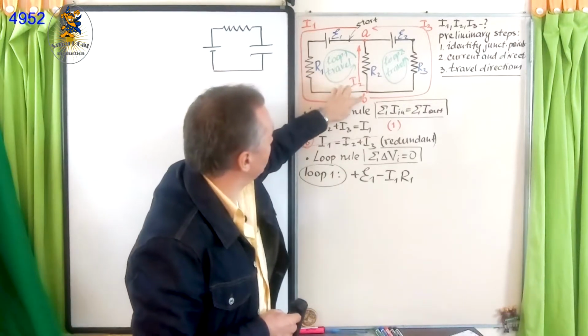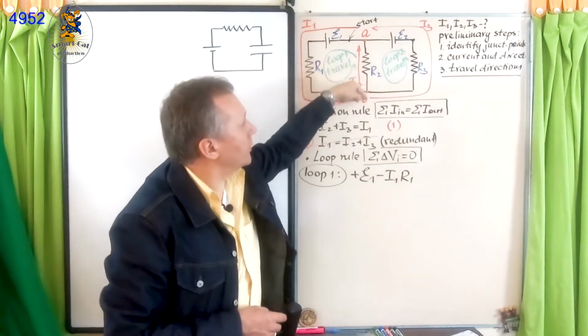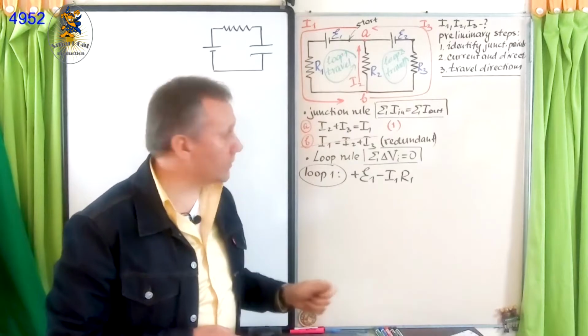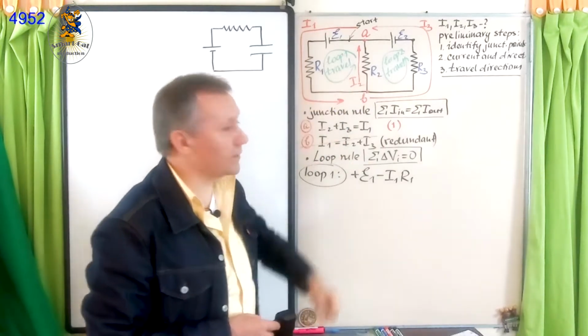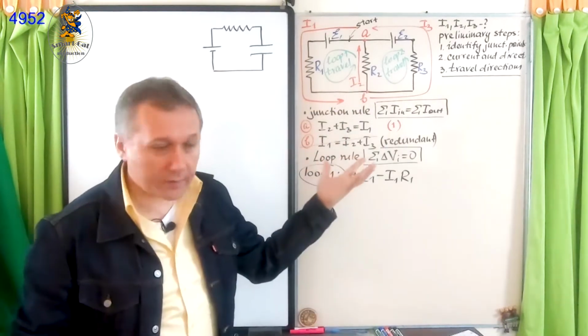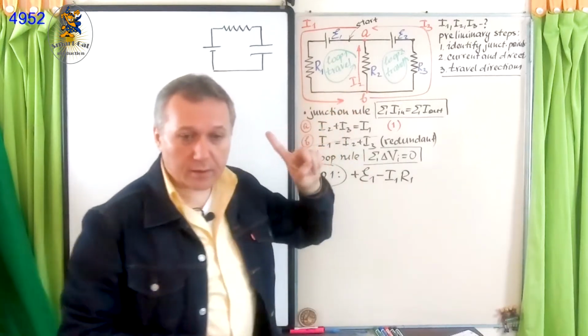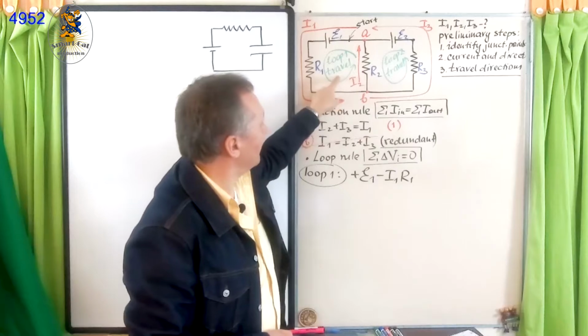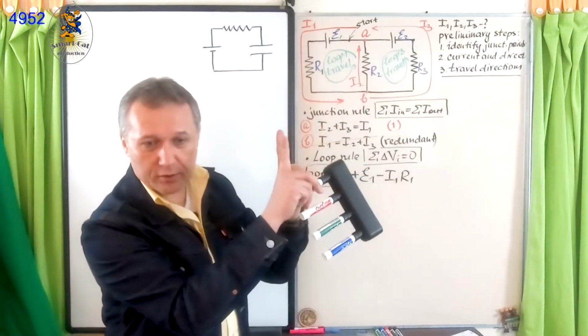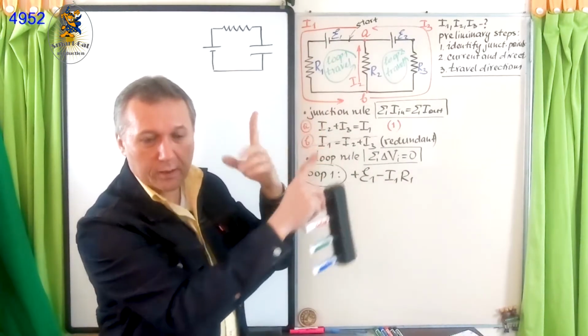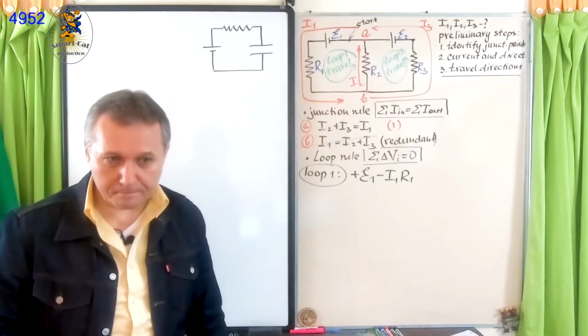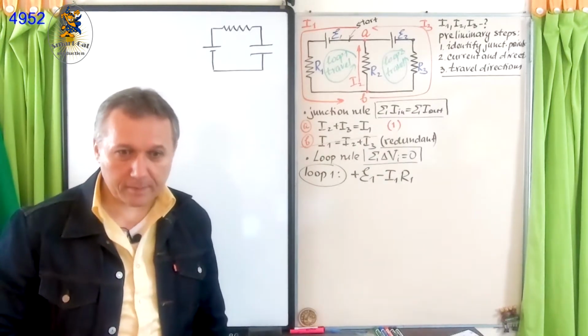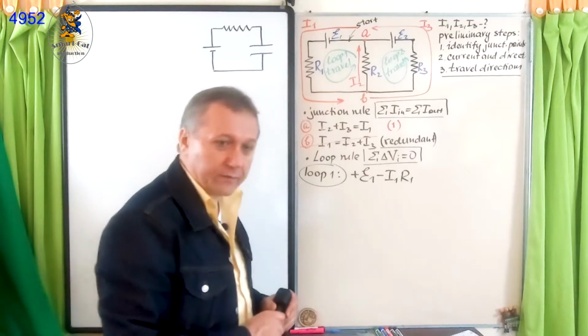Then we pass this. Now we have to go here, and now we have to go up through this small bridge, right? So now we're up against this resistor R2. So let's look at the directions. Current now is I2. So current is up, travel is also up, the same directions, travel and current. Again, the same rule number 3, which you have in your notes, right? So contribution will be negative, minus I R2.